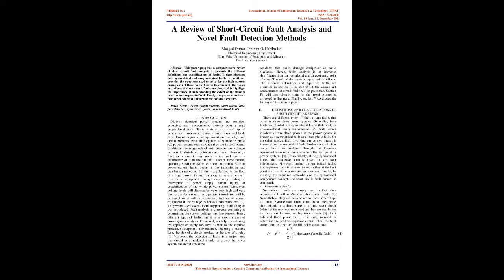Moreover, voltage levels will alternate between very high and very low levels. As a result, the equipment insulation will be damaged, or it will cause startup failures of certain equipment if the voltage is below a minimum level. To prevent such events from happening, fault analysis was introduced. Fault analysis is a process consisting of determining the system voltages and line currents during different types of faults, and it is an essential part of power system analysis.